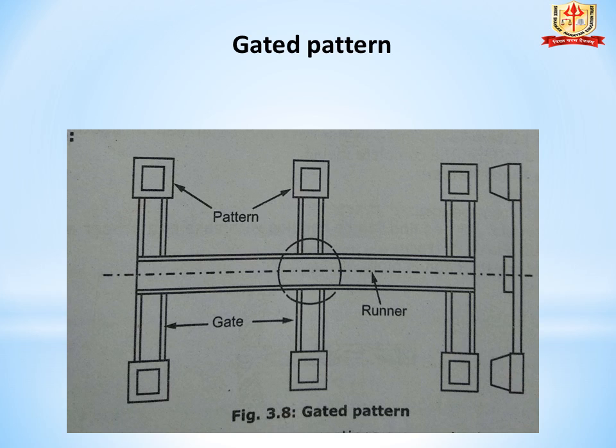The gated pattern helps to keep the patterns in a proper position relative to each other. This eliminates cutting of gates, etc. by hand. Also, higher production rate is obtained. This gated pattern is mostly used for mass production.